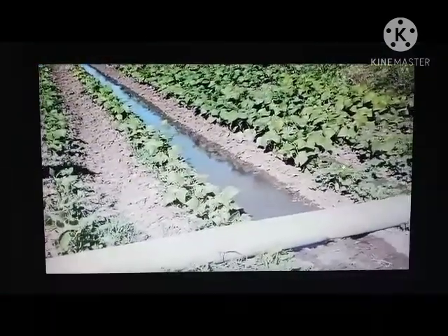Because the water penetrates so much better where you haven't driven the tractor, the system uses a lot of water, and it puts a lot of water deep. So it's important to use it only on crops that are deep rooted and can take advantage of all that water in the ground. With those kinds of crops, you don't have to irrigate very often. With the drip system we were irrigating every day or every other day, and with the sprinkler system on direct seeded crops, every day. With this furrow system, you might only irrigate every 10 days or every 2 weeks, depending on the soil type and the weather, and how much evapotranspiration there is.